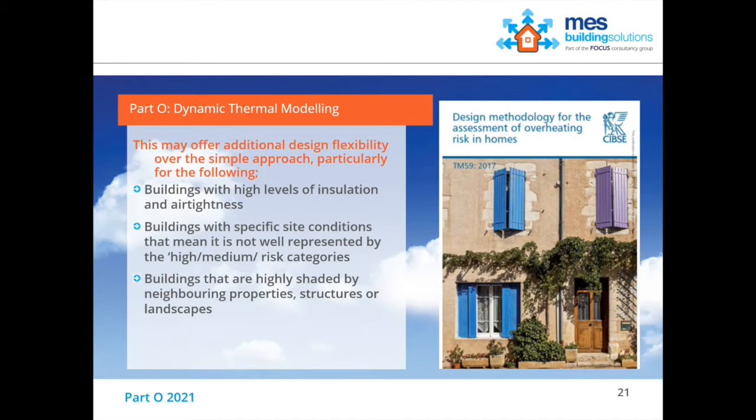The aim of the DSM approach is to give us more flexibility with regards to the design, for those buildings that don't necessarily fit the simplified approach. To a large extent, the simplified approach has been designed to work for developers who have a range of standardized house types. They can resize all the windows in their standard house types, and they know whether a house type will comply before they put it on a site layout plan.